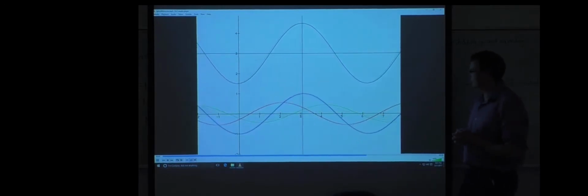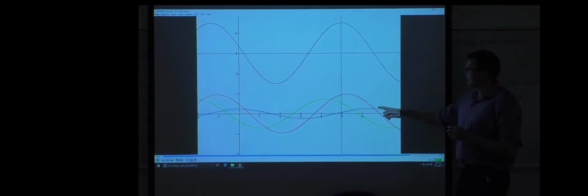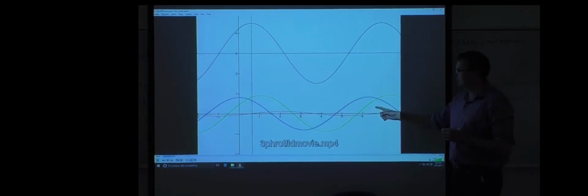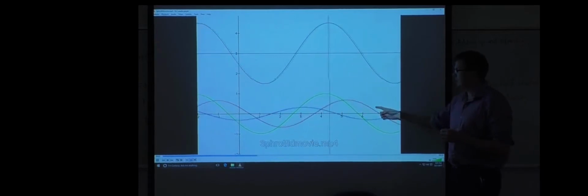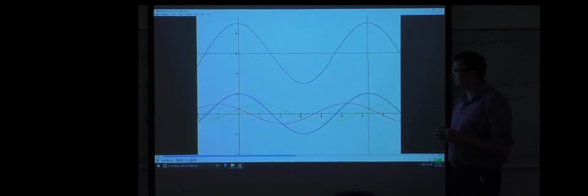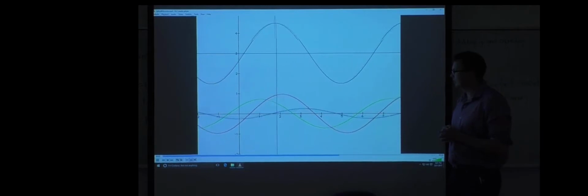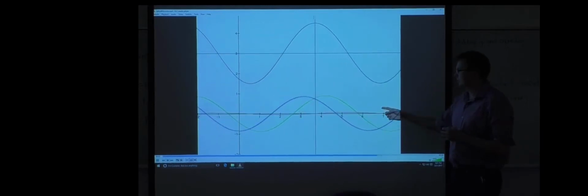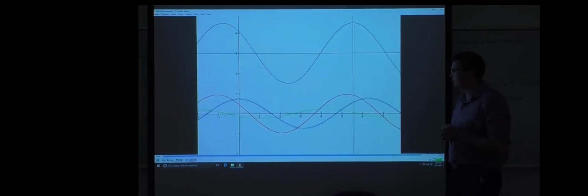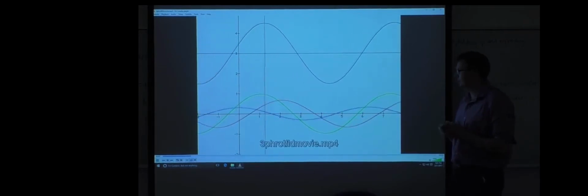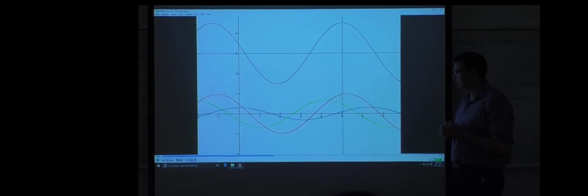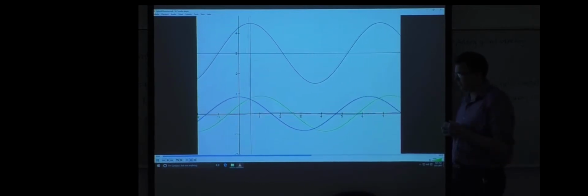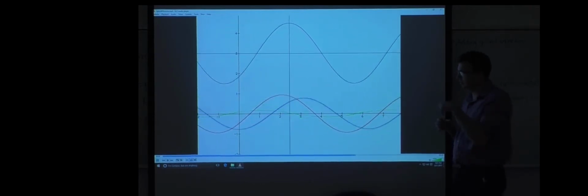But now what we're going to talk about is that we cannot easily get a perfect sinusoid. So we're going to look at how to create different waveforms to try to approximate a sinusoid, and then we'll also look at different fractional slot winding types that use higher harmonics to interact with the magnetic rotor.